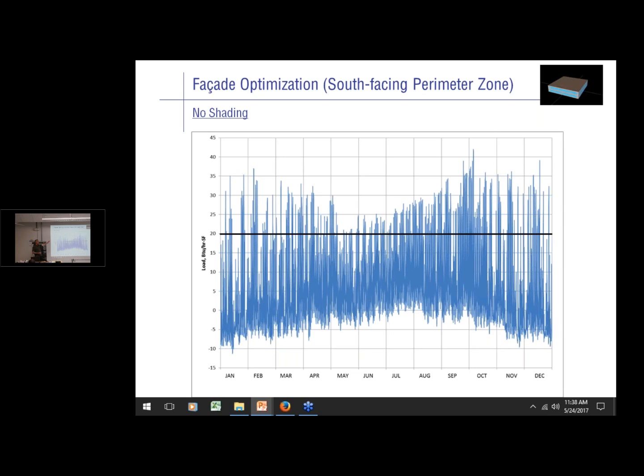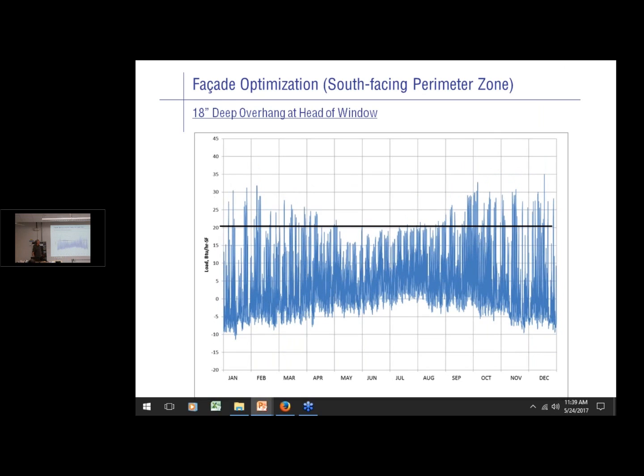It shocks some people. Most engineers are doing their load calcs on June 21. And if you did a June 21 design day in eQuest, it would not be the peak day because the solar load would be way less than mid-September to mid-October. How was your fixed shading operated in October? Yeah, well, in this case, we have no fixed shading. So this is kind of how then I start adding things.